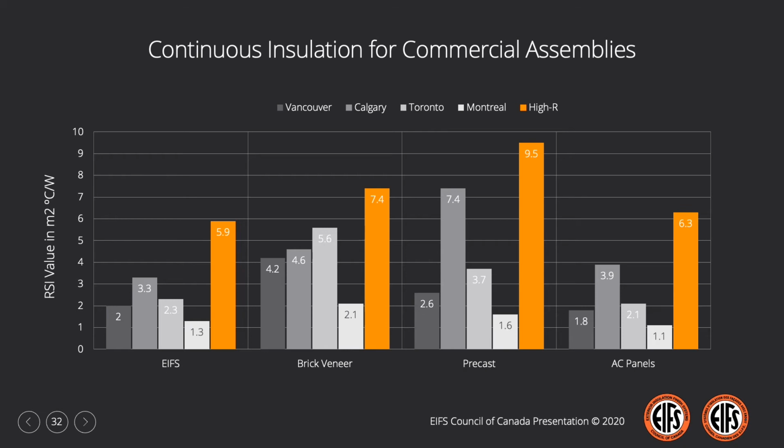That's for a variety of reasons, but suffice it to say for now that the commercial envelopes are more thermally sensitive, if you will, because of the effects of thermal bridging through the metal framing members. So, of course, we have a difference in the exterior insulation amounts required and a difference in performance across these assemblies as well.